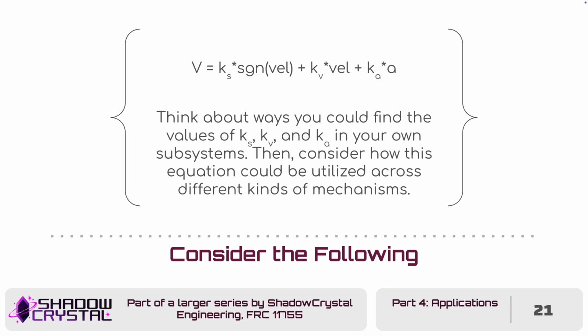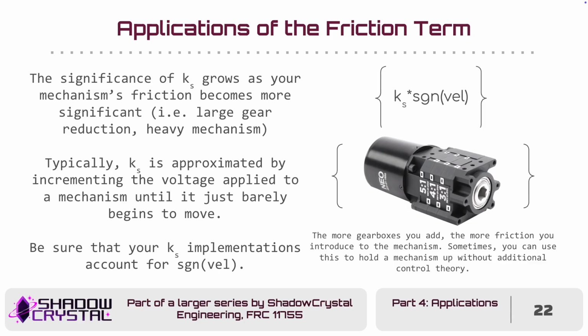Okay, moving forward. So, first we're going to consider the friction term since it's the simplest. As I previously stated, the significance of the friction term grows as you add more gear reductions or your mechanism gets heavier and you have more moving parts, because your friction is going to increase.